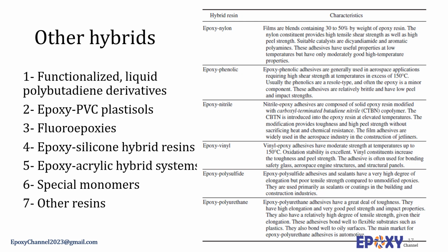The use of fluoroepoxies is most advantageous in bonding fluorocarbons such as polytetrafluoroethylene to the epoxy. Good bond strengths are achieved on fluorocarbons without the need to surface treat the substrate because the surface tension of the adhesive is reduced from about 45 dyne per centimeter for normal epoxy to 33 dyne per centimeter for fluoroepoxy.